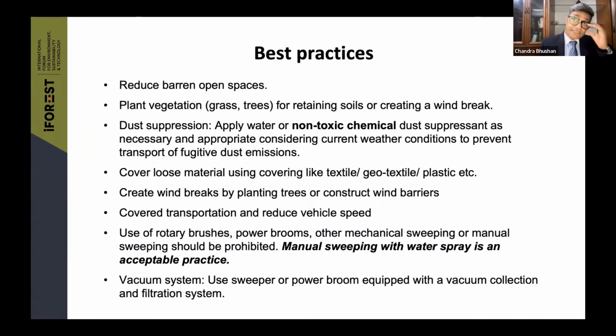What are the best practices? As I said, if you want to reduce dust generation within a city, you have to reduce barren open spaces. You have to either do biological covering, or where required, you will have to do paving as well. Whether you do porous paving or non-porous paving, depending on the situation.